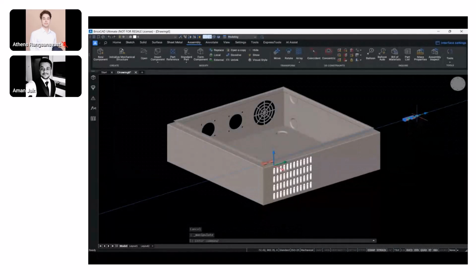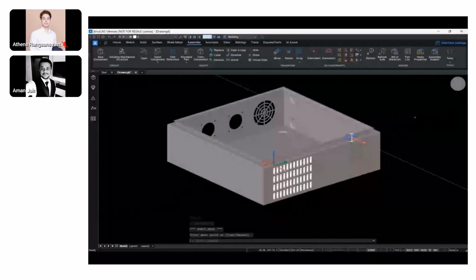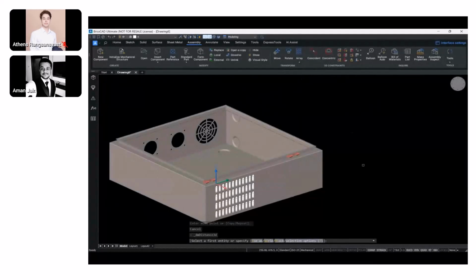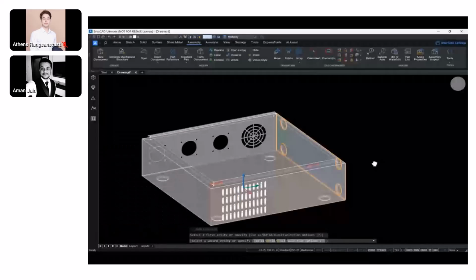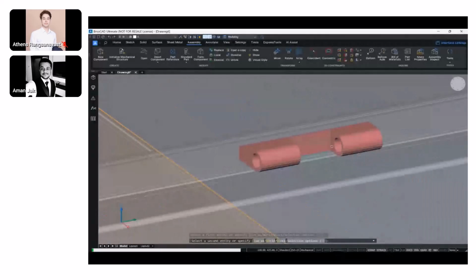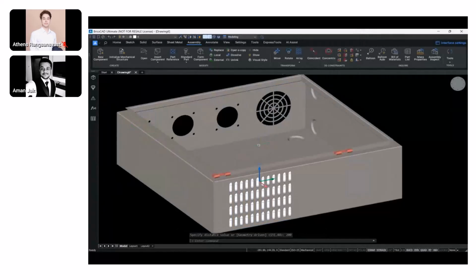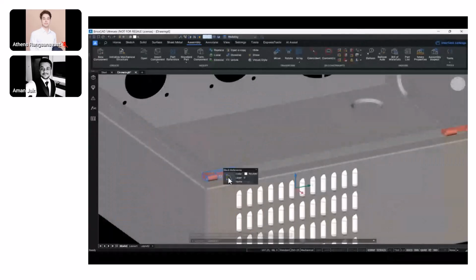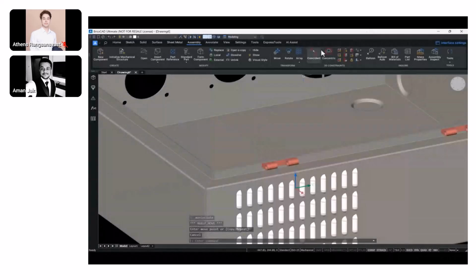And then all I need to do is give the distance constraint so that it stays in place. So this would be in reference to the constraints that we had placed for the hinge in the door. The hinges would be placed in between. That's the male female joint, right? So this would be at a distance of 200 so that it doesn't interfere with the hinges that we have in place at the door. And this again would be at a distance of 200 from this particular face. Let me just move it a bit to the right hand side. So just moving it, this is a free movement.